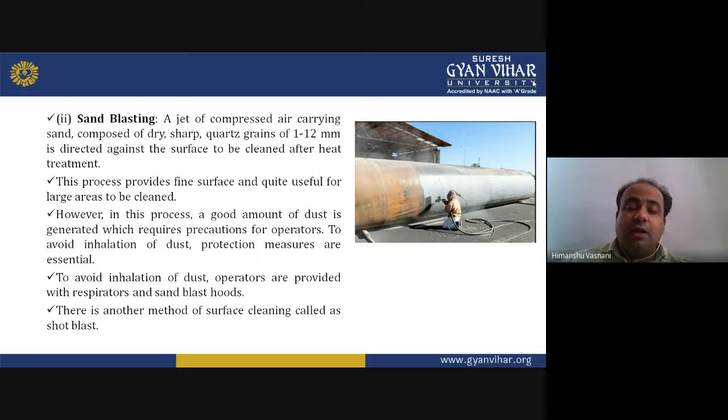In this process a good amount of dust is generated, which requires precautions for operators, because breathing problems may occur. The sand has sharp-edged quartz grains, and when you direct this compressed air on a surface, it may spread in the nearby area. So operators should take precautions to protect themselves.